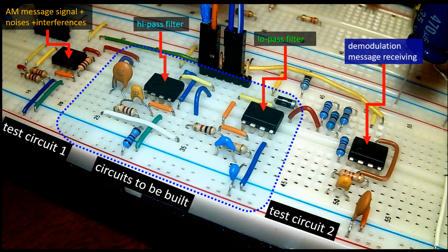In summary, this bonus project involves two additional circuits. One is to simulate signal and noise and interference. The other is to demodulate the AM signal. While the high-pass and low-pass circuits are the core of the Lab 6 assignment, the basic tests of frequency, step, and impulse responses done in Parts A, B, and C are essential but not significant in the broader context of applications. The true meaning of these circuits is the performance, such as in the simple AM modulation and demodulation demonstration.